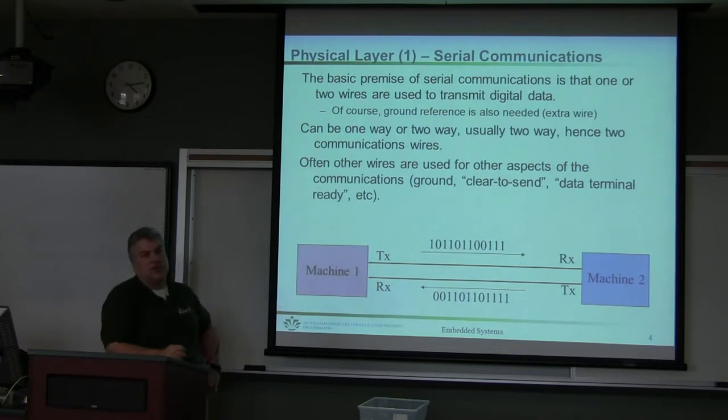Typically, when we talk about serial communications, we will use 2 wires. One for transmit, one for receive. There are some devices, like the ping you just saw, that had a very rudimentary form of data communications, right? A single bit, so to speak. A rising edge of a pulse from your microcontroller application to the ping sensor, and then the ping responds with a single pulse. That is a very simple form of serial communications. Same wire. However, we are allowing ourselves to use transmit and receive.